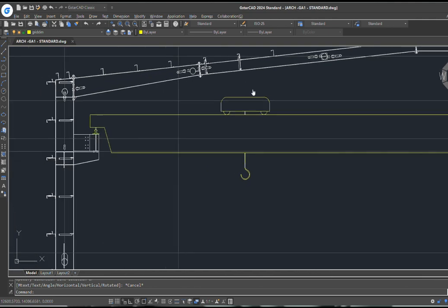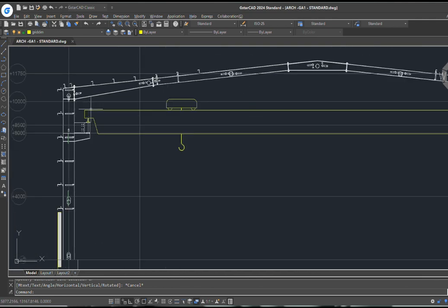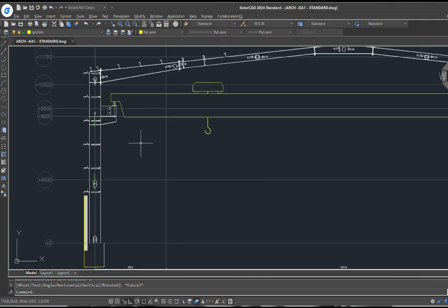So as of now it is 10 meter, but in my Staad Pro V8 model, I have taken it center to center distance 11.15. If you see the crane detailing section, you will come to know why this has been done. There will be around 250 mm kept below the finished level.